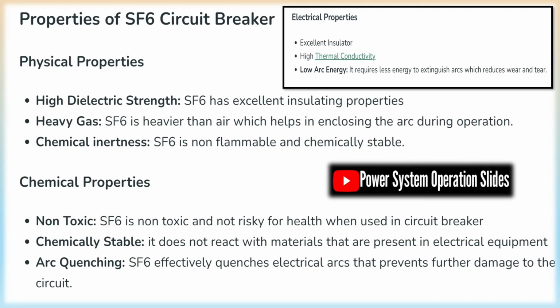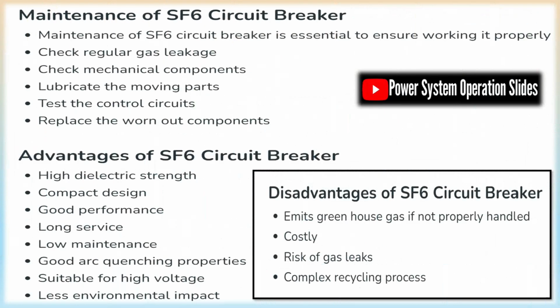SF6 circuit breaker types. At present, SF6 circuit breakers can be classified into two major categories: dead tank enclosure at ground potential, live tank enclosure at line potential. Dead tank designs can offer greater short-circuit current breaking capability and seismic rating, but are relatively bulky, require more SF6 gas, whereas live tank designs are modular and more compact.